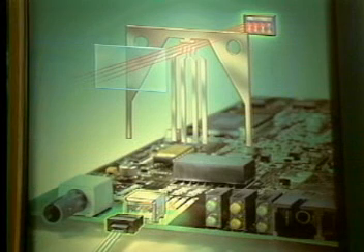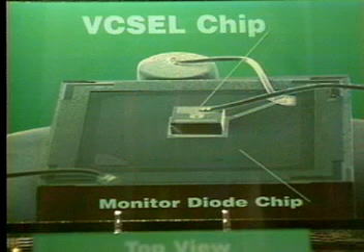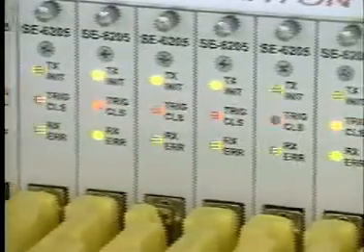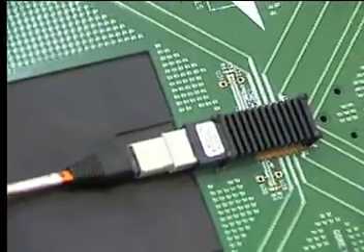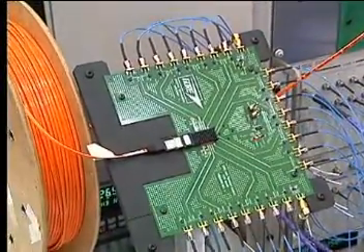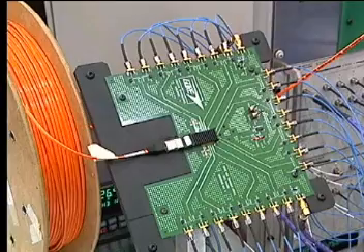The vertical cavity surface emitting laser, or VCSEL, combines the best features of LEDs and conventional lasers to meet this challenge. VCSEL devices can be manufactured by bonding wafers of gallium arsenide to form an active or light-generating region, as well as mirrors to form the laser's resonator. This is similar to common LED manufacture and results in low cost with high yield. In addition, VCSELs feature low power consumption, reliable room temperature operation, and can be tailored to provide circular beam profiles for better light coupling into optical fiber.